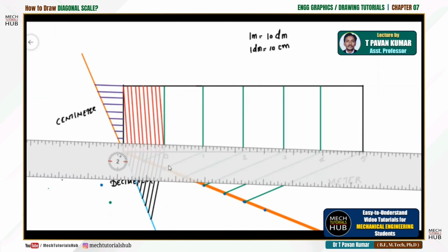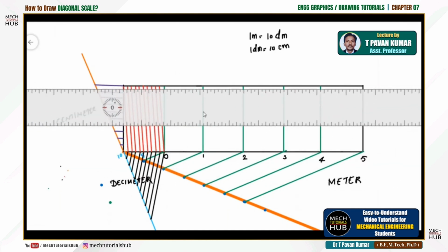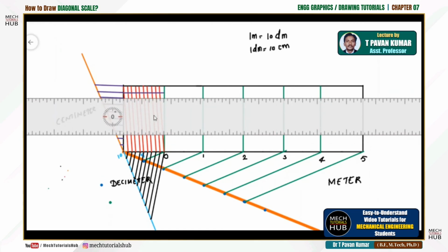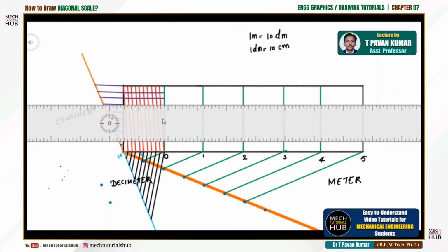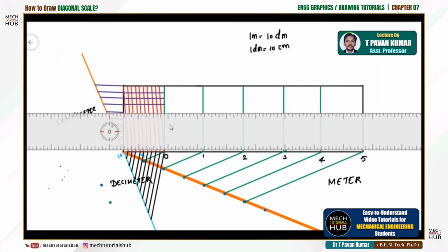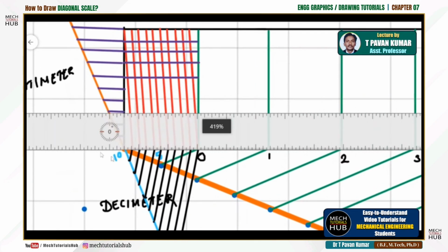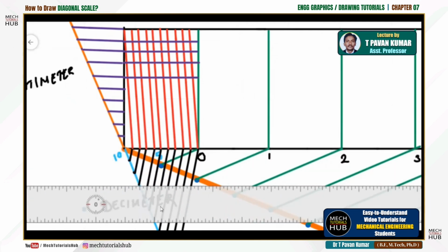After this, simply we made 10 divisions by using grey color line. Now rotate your drafter to 0 and draw horizontals at each and every intersection. Draw horizontals at each and every intersection. Number 1, 2. Draw it accurately, properly, without any disturbance. 1.5 mm is also important. So you have to be careful with whatever drawing instrument you are using. Always try to maintain sharp tip of whatever pencil you are using.